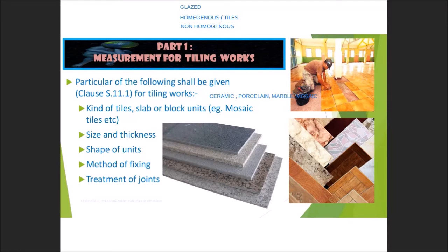1 feet is equal to 300 mm. You can imagine 1 feet with one long ruler. This is very important because sometimes a lot of construction work still uses this terminology. So you have to at least know 1 feet is equal to 300 mm. Okay. The thickness also must be stated, 8 mm, 6 mm, maximum is 15 mm. That is common. The thickness also gives you different price and quality. Normally, if you use the homogeneous style, the thickness is more.